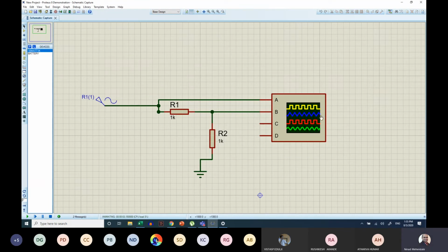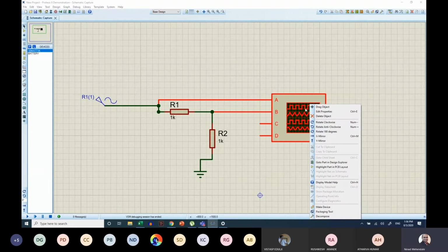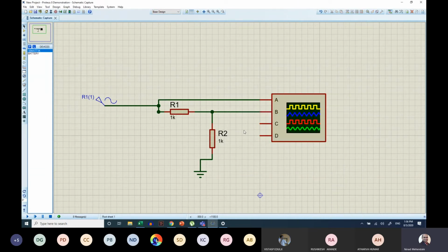As soon as you close the CRO option, the simulation will not open that window again for you. So you have to be very careful when you close the CRO button. The only way back is to recreate the entire simulation.